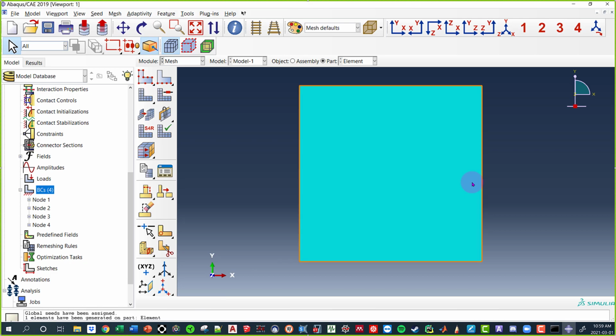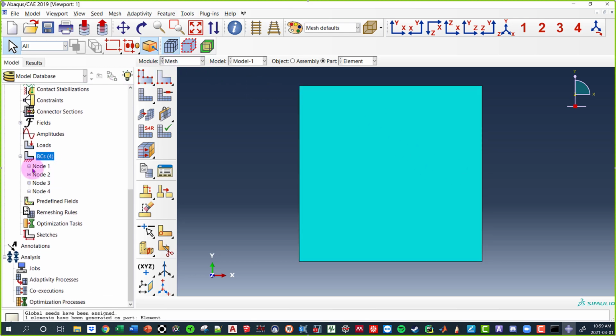All right. So remember that our element stiffness matrix entries, Kij, are equal to the force at DOF i after unit displacement at DOF j. And I know that sounds really, really crazy, but what we're going to do is start playing around with these boundary conditions.